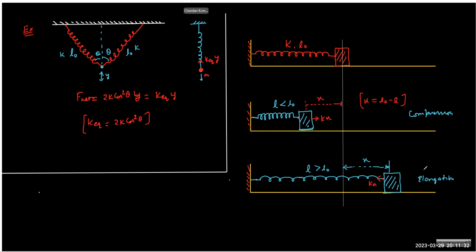So the dissipation of energy by frictional process will have three effects: heat generation, sound production, and light production. Among the three, practically we have found that the majority, 99.9%, goes into heat generation, and less than 1%, maybe 0.001 or 0.01%, only creates the sound effect and the light effect.